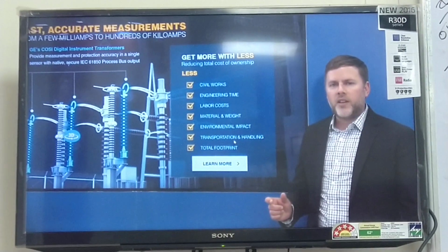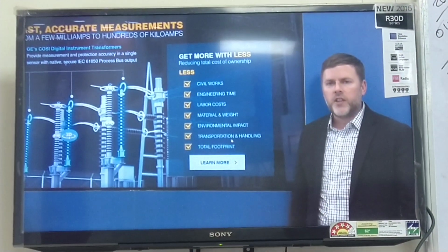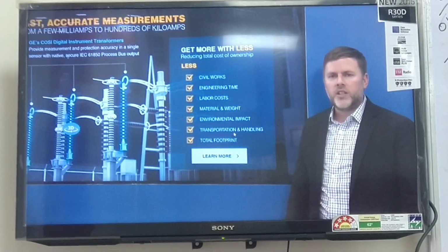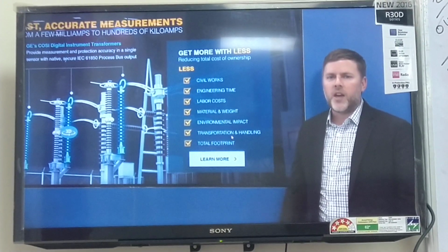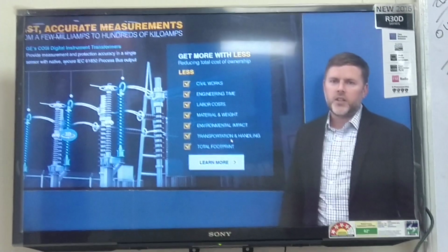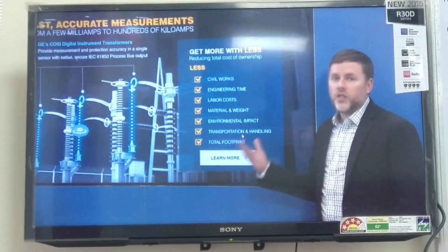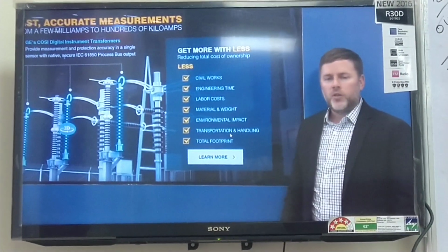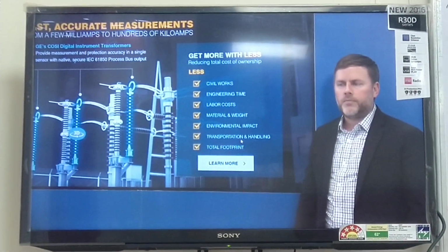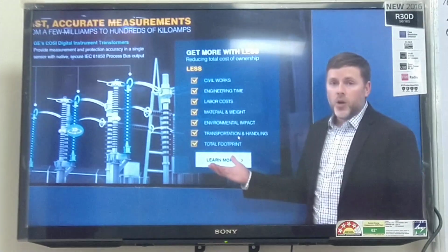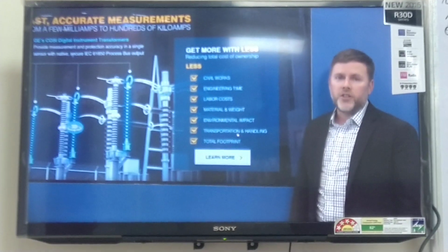There's a small amount of magnetization current flowing in and out of the transformer as the voltage rises and drops. That current could be in the range of 10 to 50 milliamps, which can't be measured with conventional CTs. The fiber optic CTs can directly measure that current, and we use relays to trip on a low current setting.